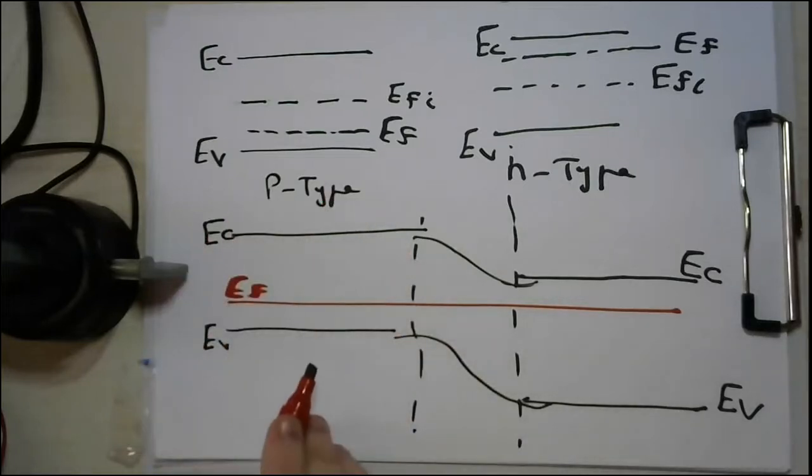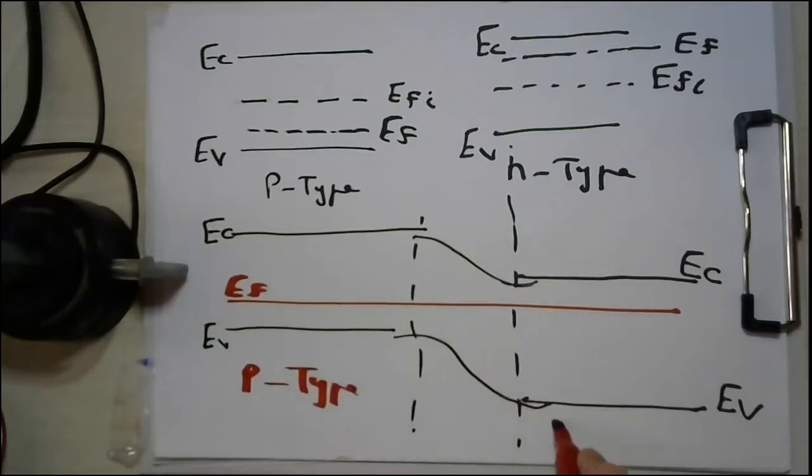this is a P-type, no worries. This is an N-type. What about this region? The first observation from this region is that it is a region where there is a tilting in the energy band. If you remember our lecture number 3, where we dealt with the drift diffusion model and the energy band diagram under applied voltage, we said that whenever you have a potential, this potential will cause the energy band diagram to tilt.